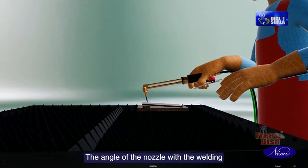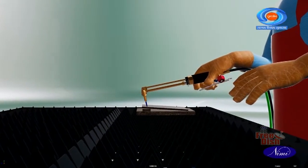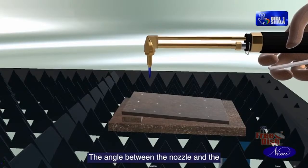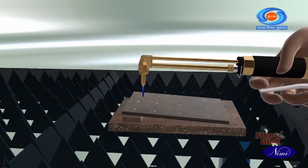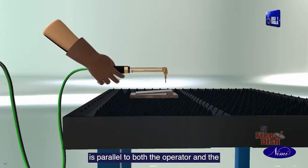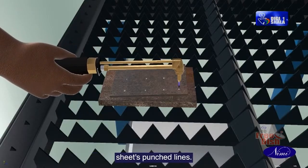The angle of the nozzle with the welding line is between 60 and 70 degrees. The angle between the nozzle and the job surface should be 90 degrees. The blowpipe should be positioned so that it is parallel to both the operator and the sheet's punched lines.